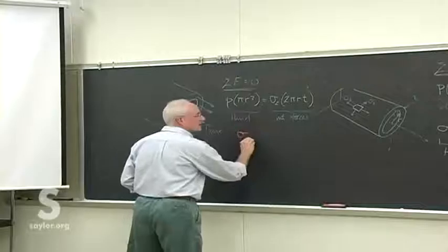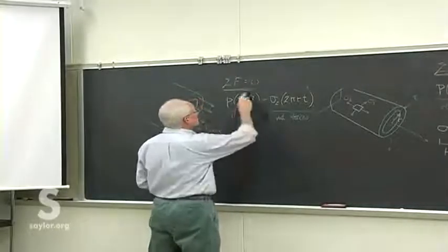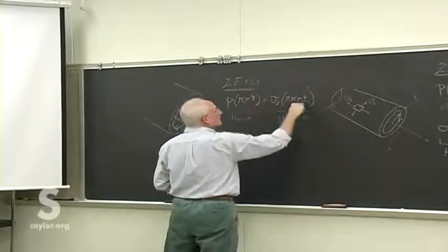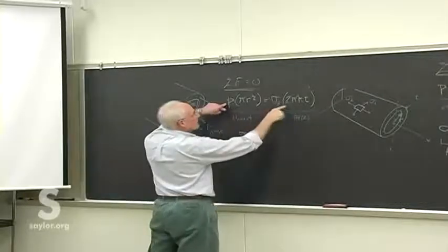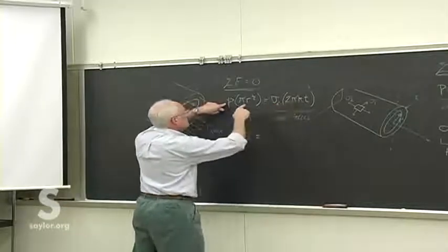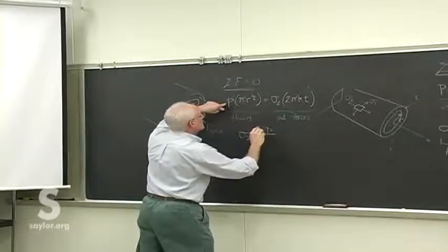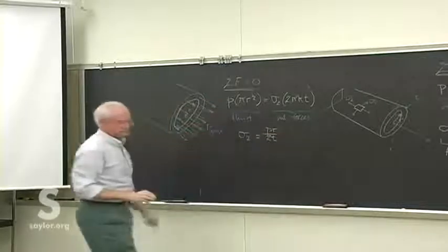And we can then solve for the longitudinal stress. Pi cancels, one r cancels, and we get then P over 2 T R. Is that right? PR? No, P times R over 2T.